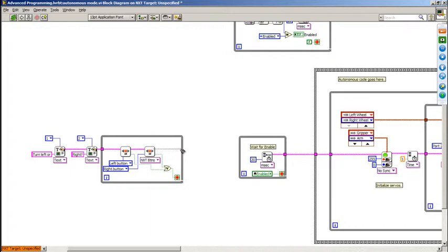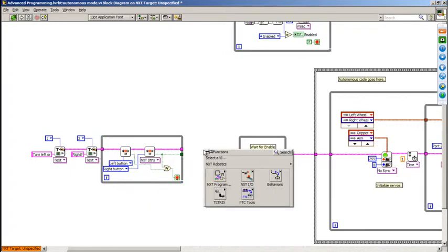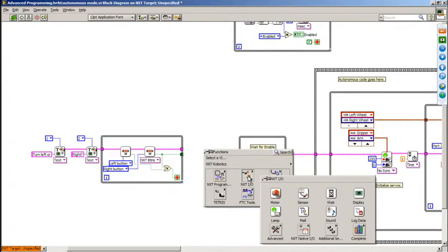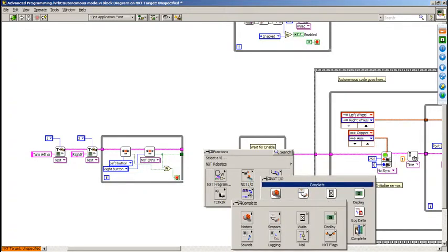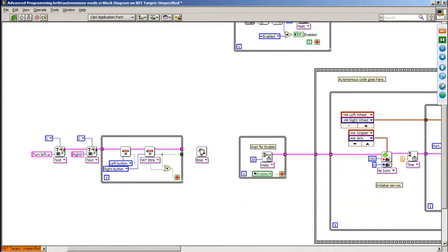Taking our NXT terminal out, we're going to make a decision and store the result as to whether the right button has been pressed. So this right button is coming out of this Boolean wire, so we're going to take it to the edge of the terminal, and now we're going to store this in one of the Boolean flags. The Boolean flags are available on NXT.io, complete, NXT flags. And here we choose whether we're going to set or get. In this case, because we're writing, we're going to do a set NXT flag function.